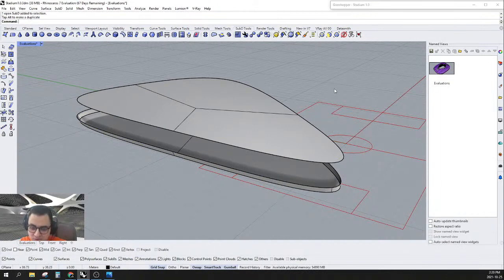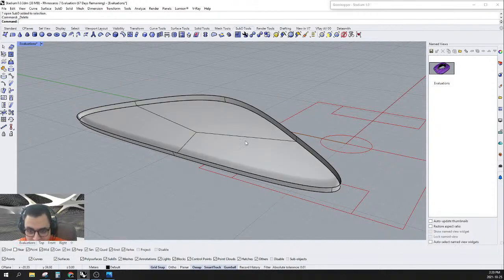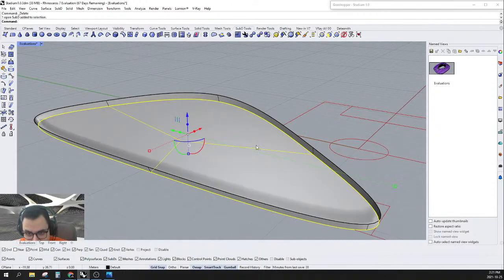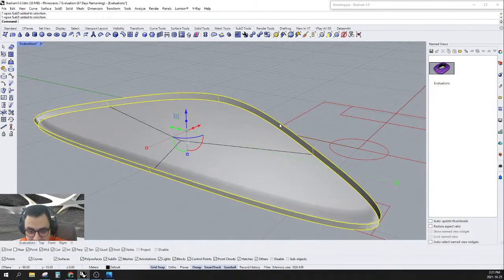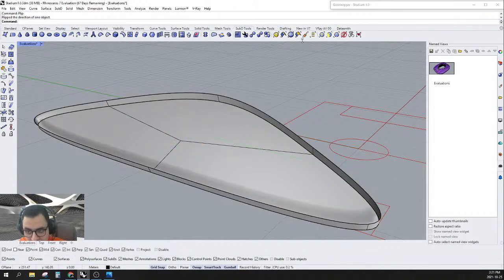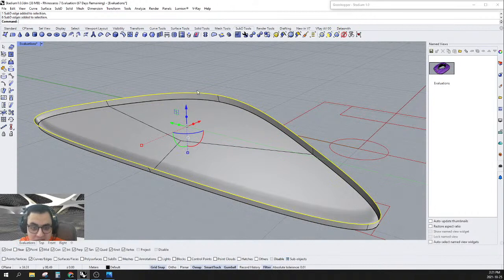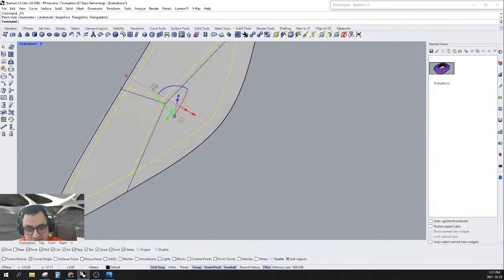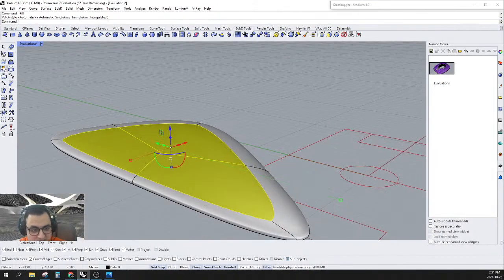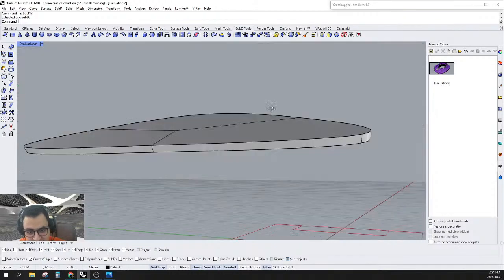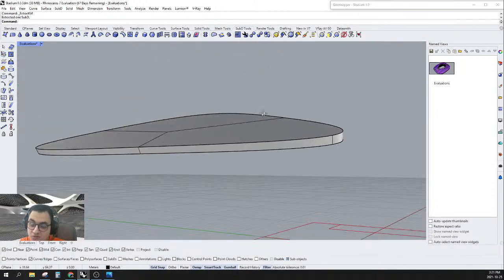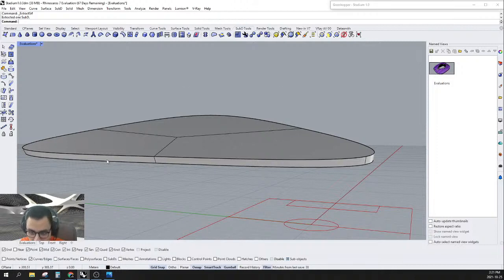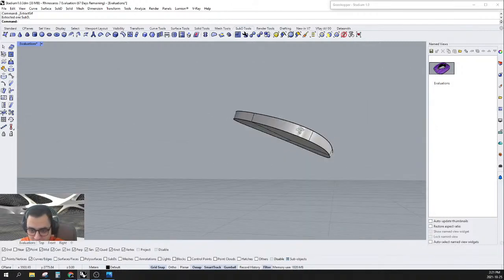And also, I don't want to move this up and start dragging the vertices. This will not help, especially if there are too many of them. So now, if I want to create the same surface in here, I will simply select this one and flip it. So now it's flipped. I now select this and again fill sub-D hole. Okay, now you can see that they are all facing the same direction, and if I simply extract the surface, now both the surfaces are fitting exactly, and you can modify them both at the same time.